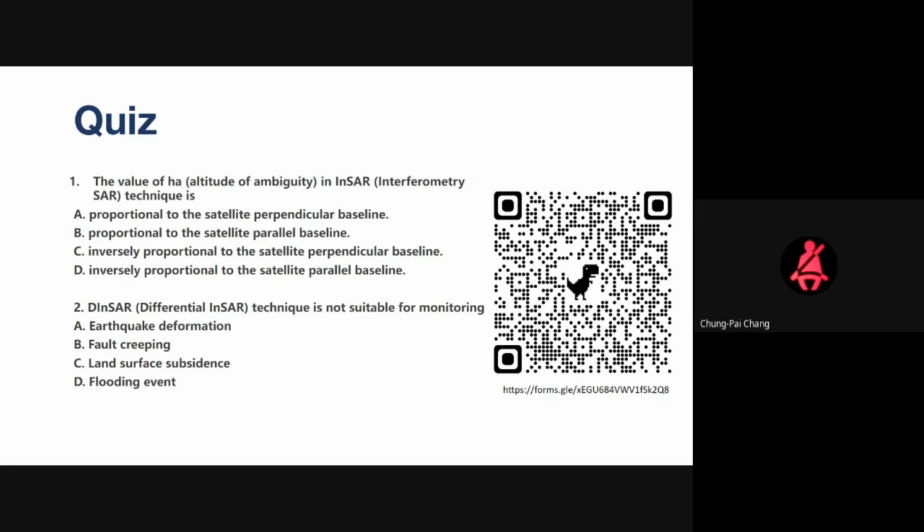That is much more rapid than the LiDAR system, because LiDAR scans one point by one point. That is what we call the data cloud, so the calculation is quite a waste of time. But by using the airborne radar, if you scan at the same time with two radar sensors, you can generate the topographic map very, very fast. So each one has its advantage. For the deformation observation, we still have to use the satellite data, I say spaceborne radar. But for others, for example, to generate a local topographic map or for some urgent event, of course you can use the airborne radar.